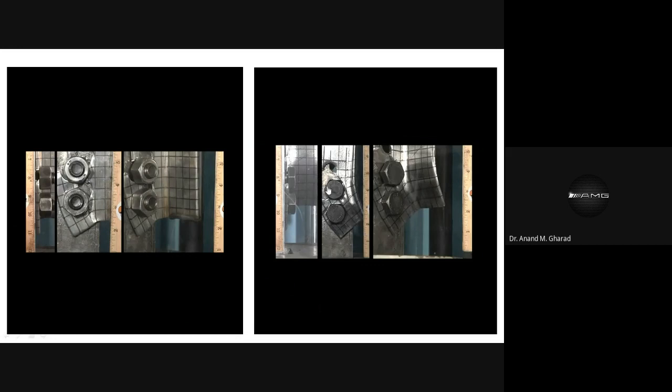One was this, and if you have observed, the failure that is in the perpendicular direction, that was from the toe. Okay, isn't it? That started from the toe portion of the angle section, and the shear plane is like this only. Over here also the shear plane is like this. Okay, but the weaker plane, you can assume this to be the weaker plane. In this weaker plane, it started from the toe portion of the angle section, right?